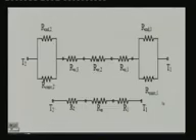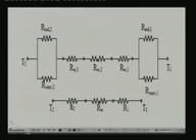So we can write a radiation network now. I hope you remember the physical model. Initially we have the temperature T1 of room 1, then two modes of heat transfer taking place simultaneously. One is radiation, the other one is convection. So you have radiative heat transfer and convective heat transfer. We write it in the form of a network with parallel connection because they are happening simultaneously. So you have two resistances in parallel. One is radiative resistance, the other one is convective resistance.